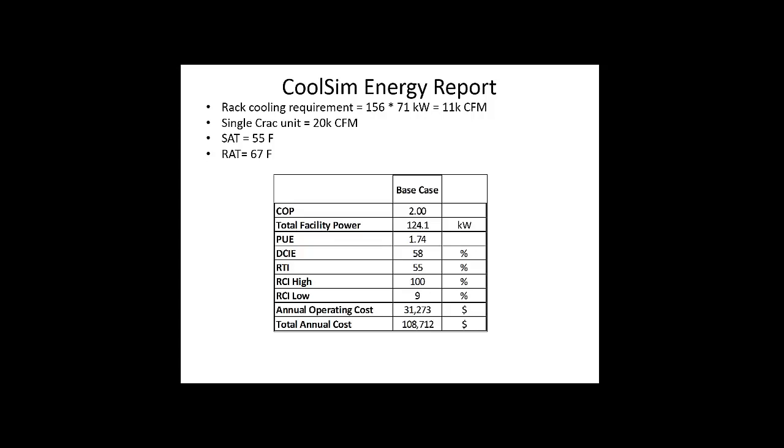Yes. I'd like to also point out that if you're running very cold and you have cold return temperatures, one of the things you run into right away is that the capacity of your cooling system degrades. Oftentimes you buy these cooling systems based on a tonnage, that's the old English system. Say it's a nominal 4-ton cooling capacity unit. Well, that assumes that the return air temperature is in the 80s. If it's not, then it's not a 4-ton unit. It's much less than that, and it declines pretty quickly. Furthermore, it has to run a lot harder, and that means energy, and of course, it reduces its life.